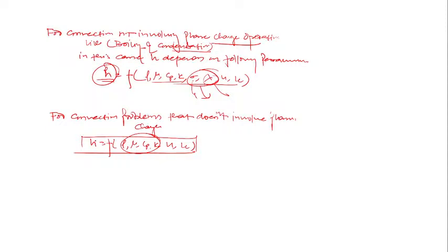Then the heat transfer coefficient depends upon the velocity and Lc, and the velocity will strongly depend upon the types of flow field. Clear? Which types of flow: laminar flow, turbulent flow.